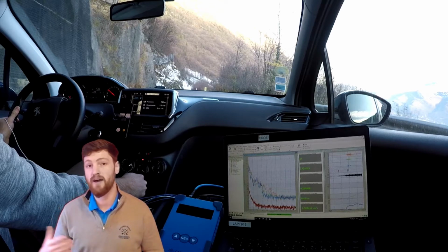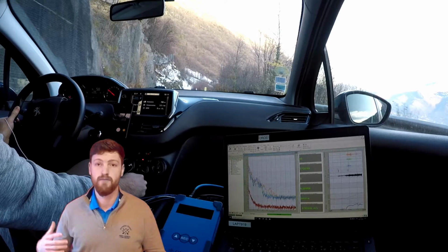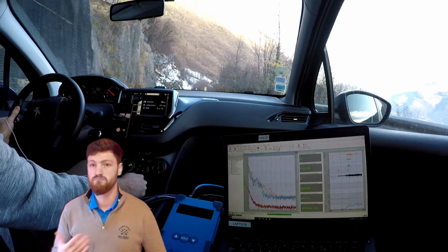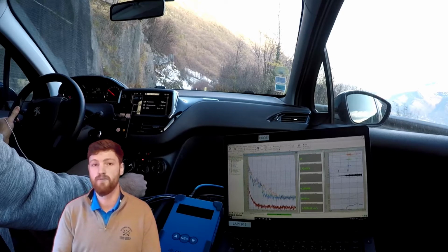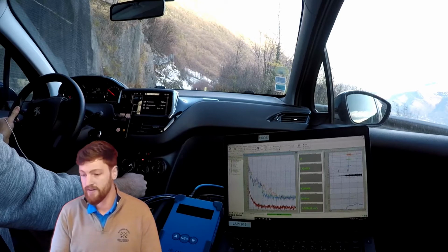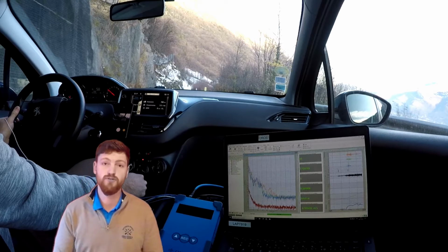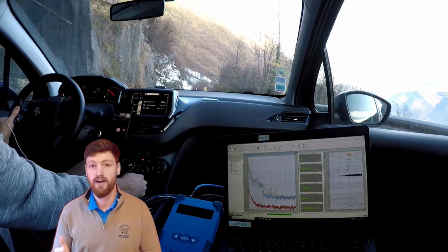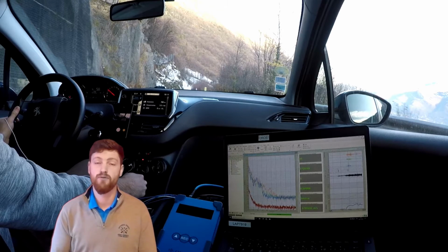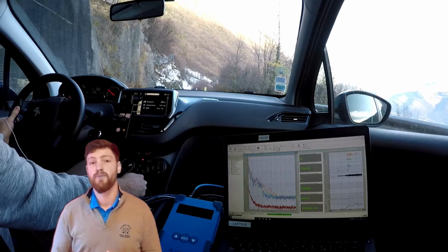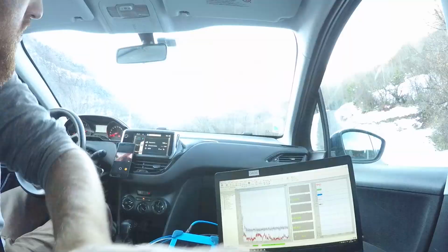And we also have a microphone in the car just to study the acoustic pressure. And for the measurement, we use an OR10, on my right. It's an 8-channel analyzer. And we also use a computer with NVGate, where we will have in real time indicators, FFTs, time signal, and so on.